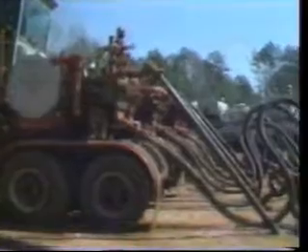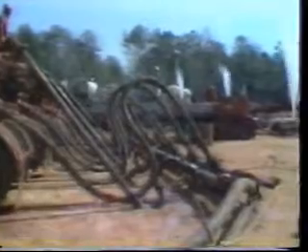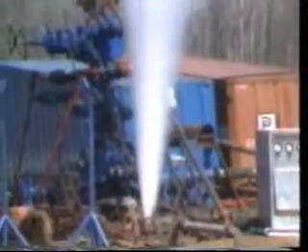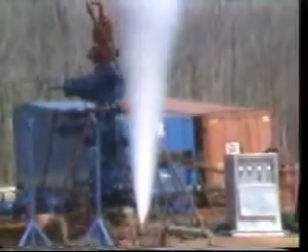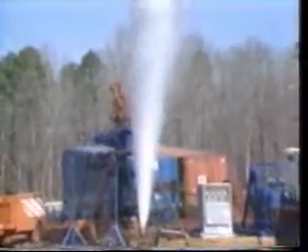Fractures are not easy to model analytically, since the conventional analysis of pressure transient data is based upon theory and procedures that assume, among other things, that the formation is homogeneous with constant permeability and porosity, and that fluid flow in the vicinity of the wellbore is radial. Obviously, any reservoir heterogeneities, and this includes fractures, will cause the pressure behavior of the well to deviate from the behavior predicted by conventional pressure transient analysis methods. And so we need to find out just how the pressure behaves in a hydraulically fractured well in order to avoid seriously misinterpreting the pressure transient data.